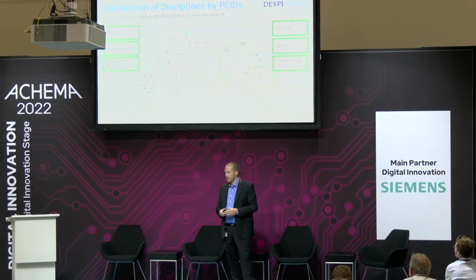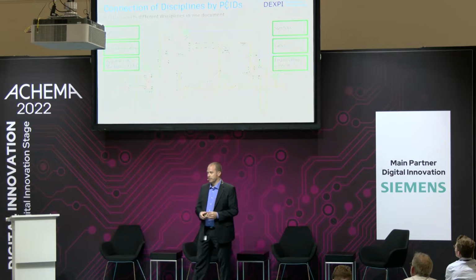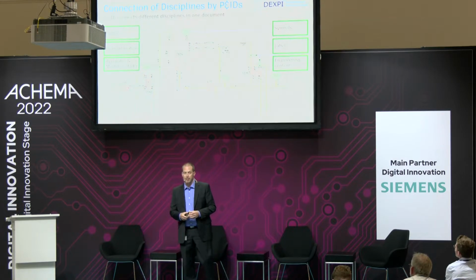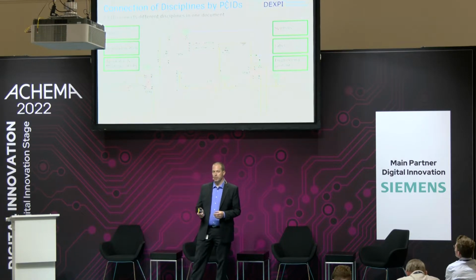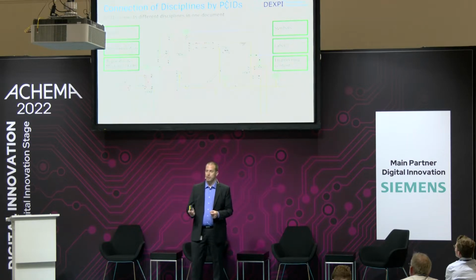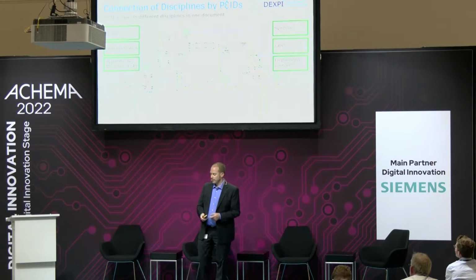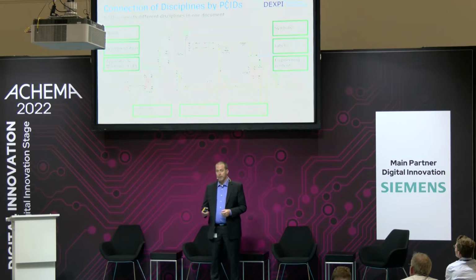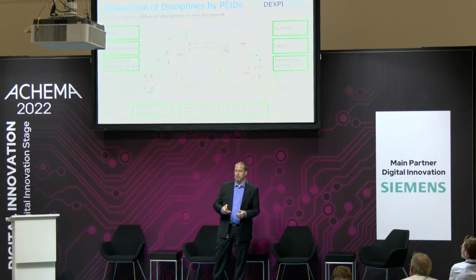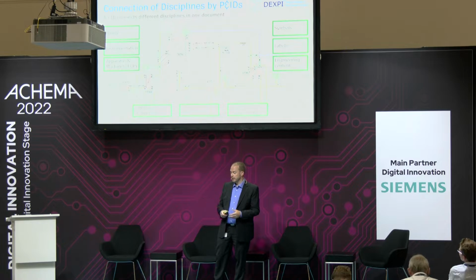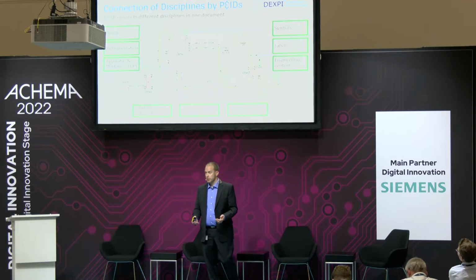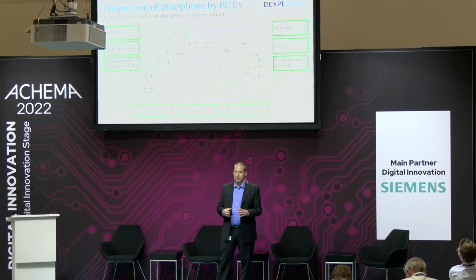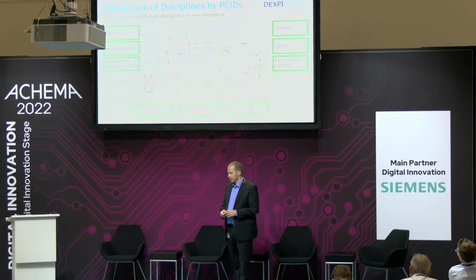And then we also have special things on these P&IDs. We have symbols, we have labels, and that's the most important thing. Behind all these graphical symbols, we have the engineering information. We also have other things like off-page connectors where you connect different P&IDs together. We have special annotations, and we also have the title block, which is also very important.